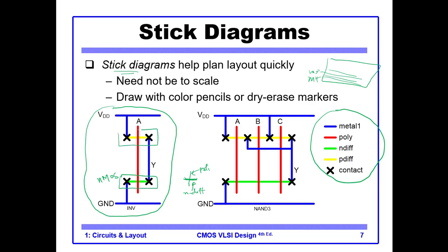So here you see this is a PMOS, and the poly lines are connected and labeled A. So this is our source connected to VCC, our drain connected to the drain of NMOS. Okay, so this is our output Y. So what is this? This is basically an inverter, a CMOS inverter.